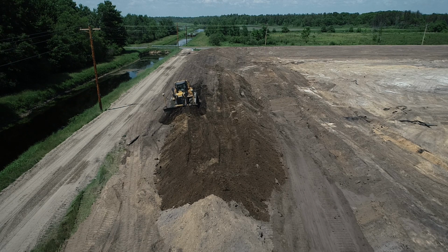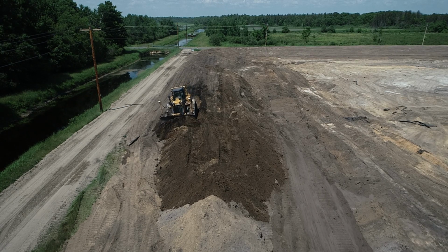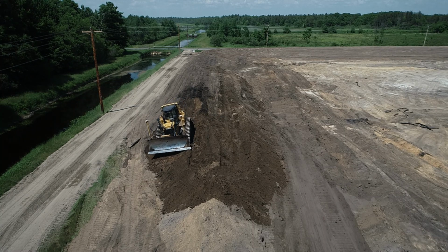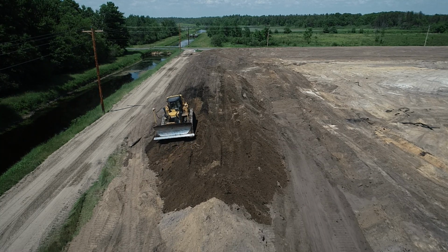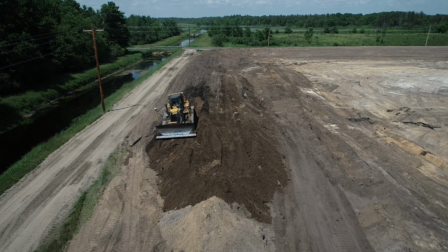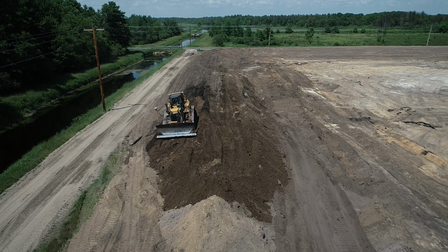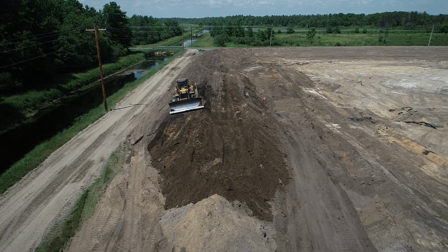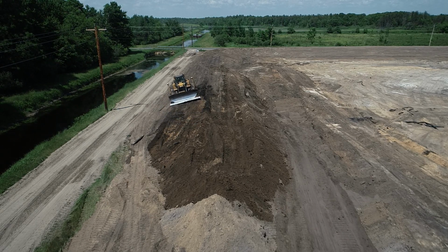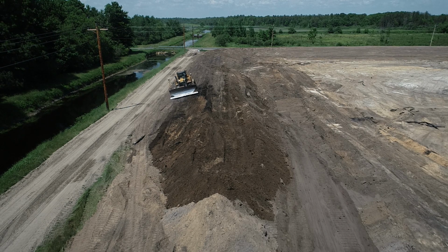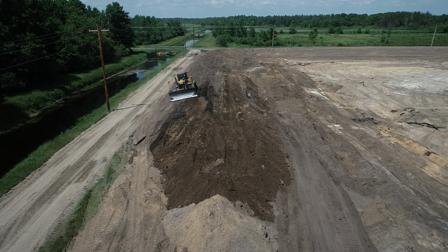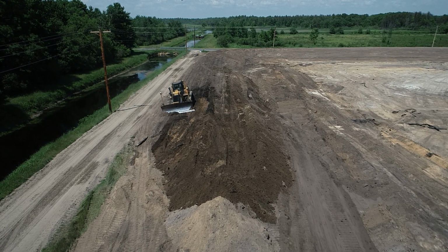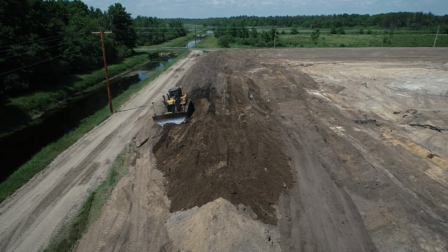Begin working or pushing material and always maintain a safe distance from all area hazards. When backing up, make sure you have a good vision of the work danger zones, noting all workers and other equipment or vehicles in the vicinity. Remain cognizant of your position on a bench, stockpile, or waste pile. Eliminate distractions while operating equipment. Stop if you need to, eliminate the distraction, and then continue your work.